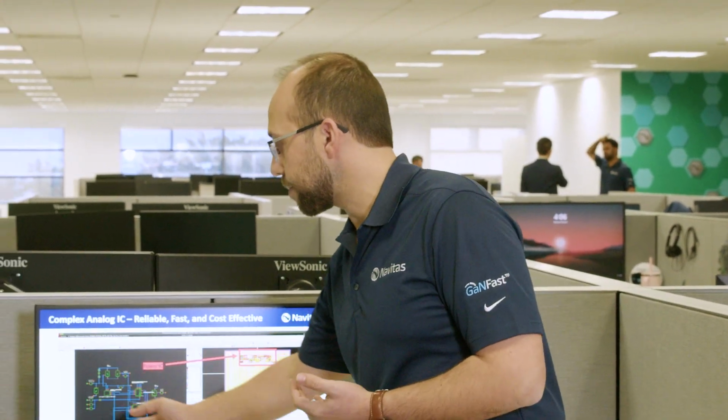At Navitas here with our proprietary PDK, where we're able to place not only 650 volt transistors, but low voltage transistors, resistors, and capacitors as well, we can create systems that do away with all those pitfalls. We can put the gate driver and other analog signal processing components monolithically together on the same integrated circuit. And what you see here is a schematic of what I'm suggesting.